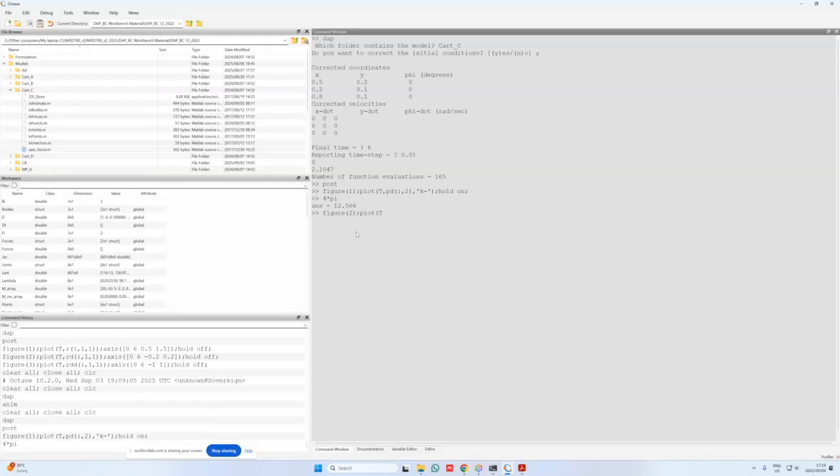I'm going to plot it versus time again, and when I plot the linear velocities, I use RD. It's going to be for all time steps. It's for the second body, body 2, which is the rear wheel, and it's in the x direction, so coordinate 1 that I'm plotting over there. And I can use a black line for this as well. I'm just going to say hold on as well so that I can compare the results to that of cart D.